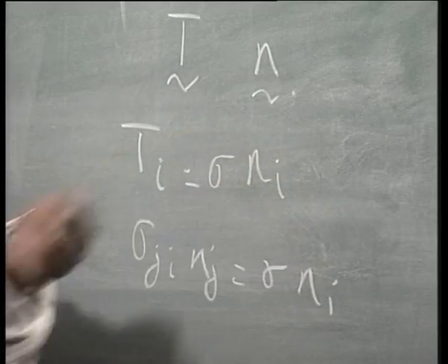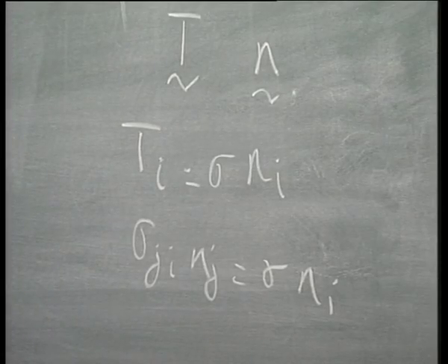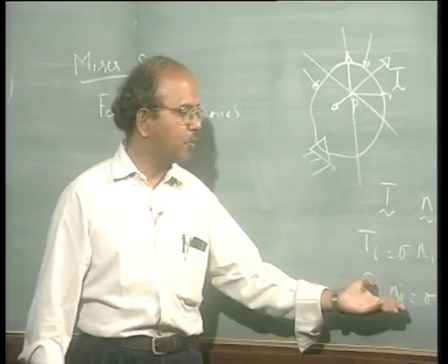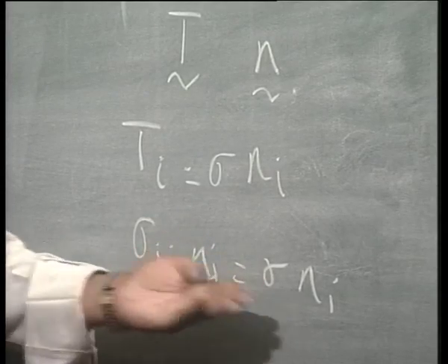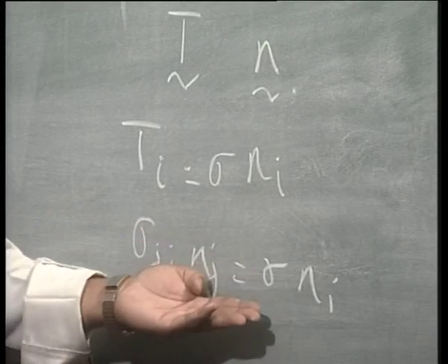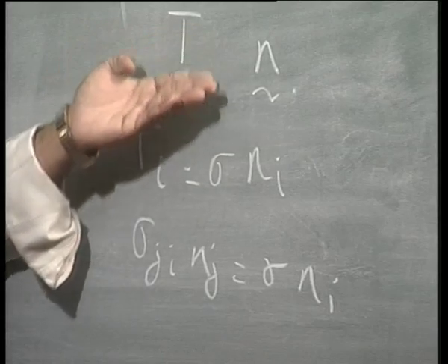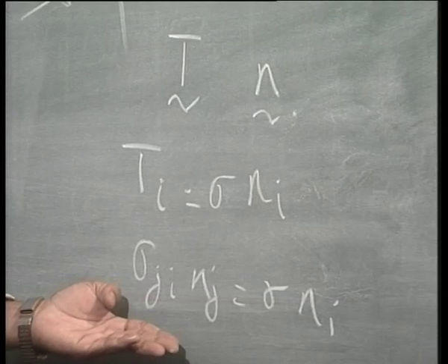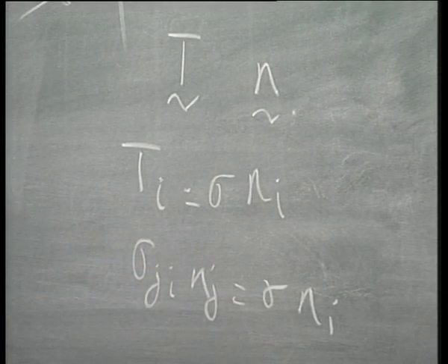They are nothing but the eigenvalues of the stress tensor sigma. Since we have shown a lot of properties for sigma, it is symmetric, and we will define many more properties later, it is possible to say that this sigma has eigenvalues, and hence that they are principal stresses. In other words, principal stresses come about because there is a property called eigenvalue for this matrix or tensor sigma.